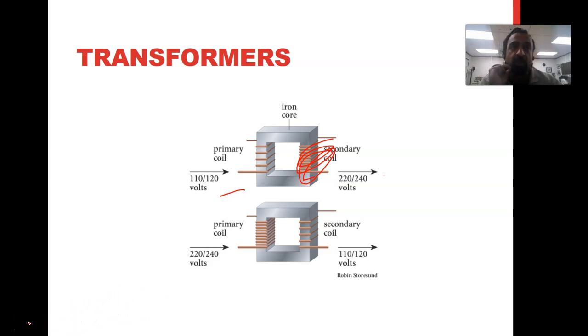So transformers, we will be using 2 types of transformers, at least in oil burners. We will have an AC transformer that transforms 110 volts to 24 volts, to operate the control. Most controls operate at 24 volts, and you would like controls to be low voltage because they do interact with us in the living space. So you don't want high voltage there, and it's better for safety.